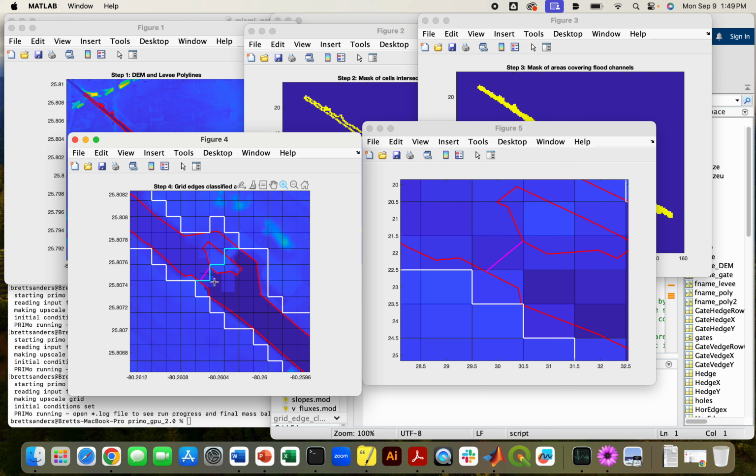Okay, so this script shows a completed set of grid edges that are used to represent this canal gate. A note here that in this particular test problem, the hydraulic infrastructure is more complicated than how we're setting up the model. There's a gate here, there's a pump over here, and the red lines represent banks of channels. And instead of trying to deal with a complicated setup where one side is a pump and one side is a gate, we just called the whole one big thing a gate, and we're going to give it an ID.